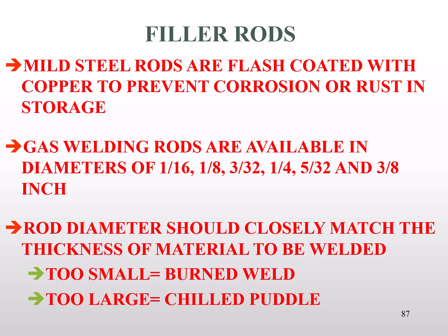If it goes into our weld, it'll corrupt our weld. So the way they protect the filler rods is they flash a very thin coating of copper on top of the mild steel. What this does is keeps the atmosphere from getting to the steel filler rod material. And if no atmosphere can get to it, it can't rust and ruin the rod and corrupt the weld.